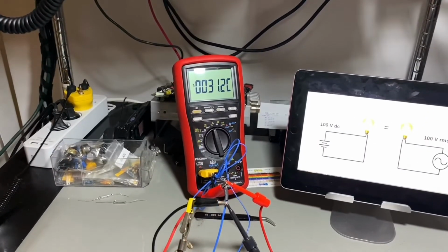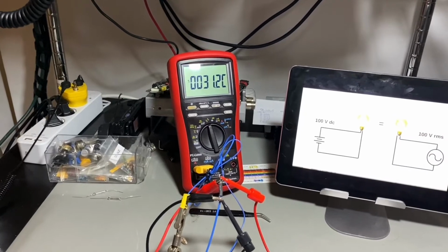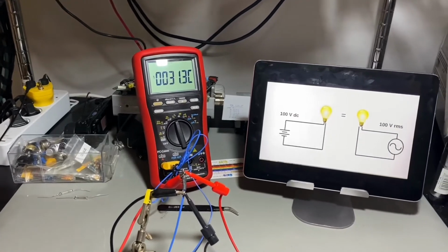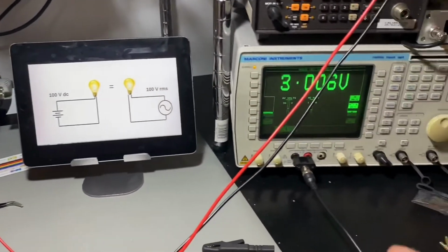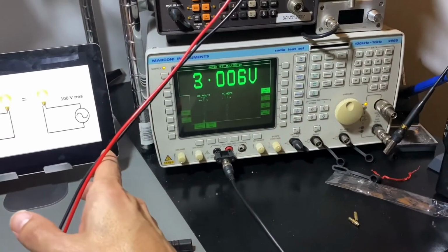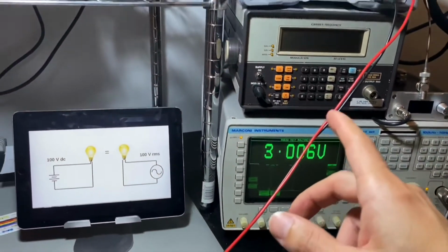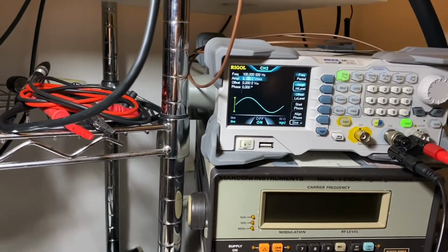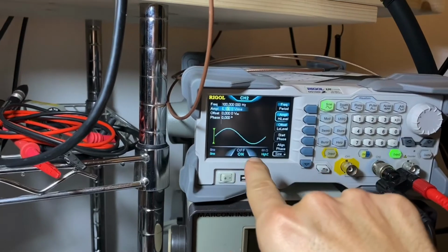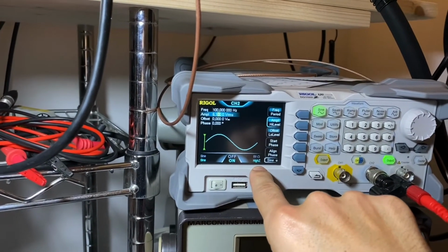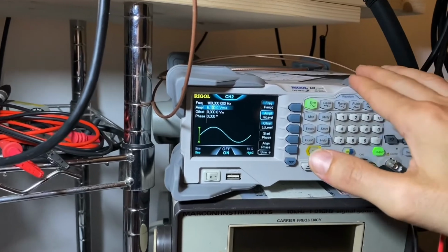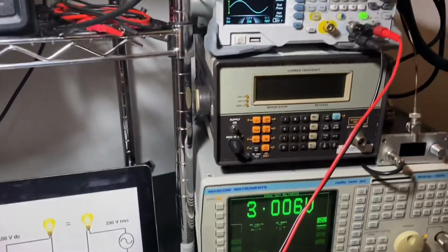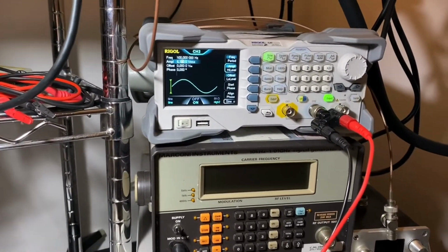Okay, now the temperature is reaching its equilibrium, 31.1, 31.2, 31.3, which is pretty much the same result we had before. The AC voltage on the cables is 3 RMS. So we are in fact giving 6.1 here, because we are set for high load impedance. The internal impedance is 50 ohm, the load there is 50 ohm, so we are pretty much dividing by 2.